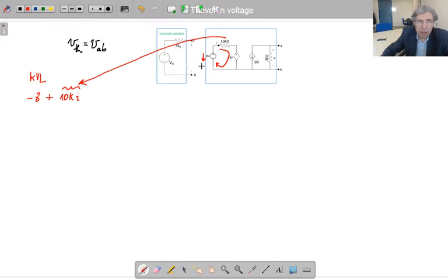And the last one is the dependent voltage source, a voltage controlled voltage source. Its current reference is downwards according to passive sign convention. So the directions are the same, plus the voltage of this element. The voltage of this element is equal to V. V is VAB, the voltage that we are going to calculate. So the voltage of this dependent voltage source is going to be 3VAB, equal to 0. So we wrote the Kirchhoff voltage law equation for this loop.